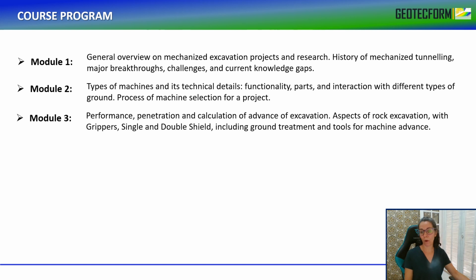Then we go into rock excavation. We have to consider that 9 out of 10 TBMs around the world are EPBs, so this course has a little bit more content on the EPB machine. But I'm still going to look into rock excavation with grippers, single and double shield, talk about ground treatments, and then all the innovations and the tools available today.